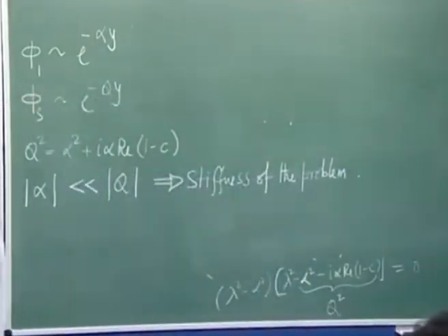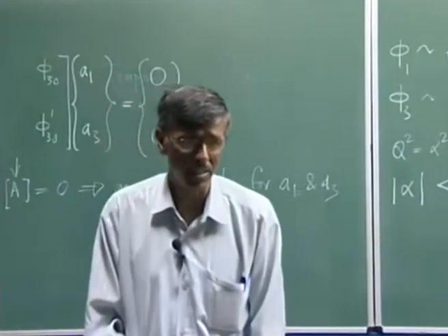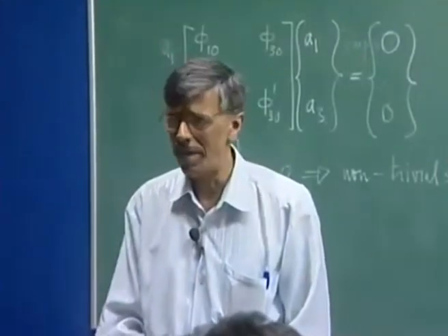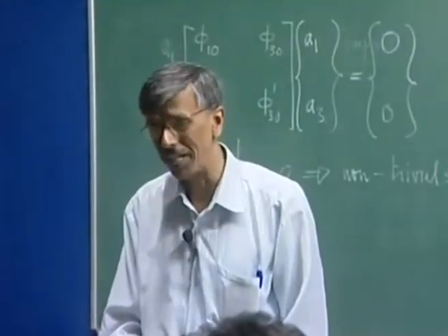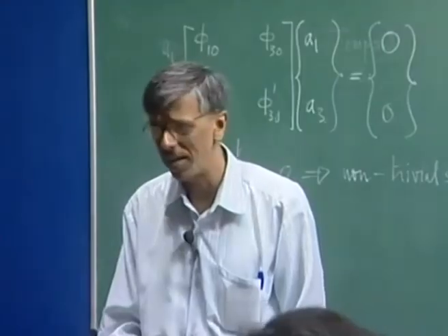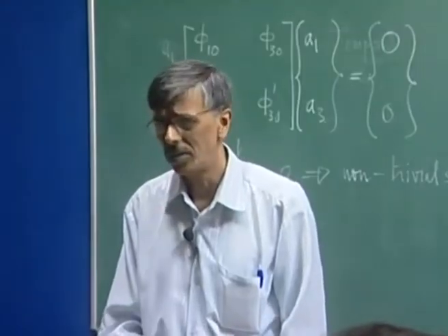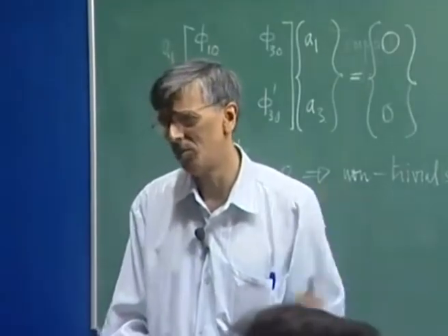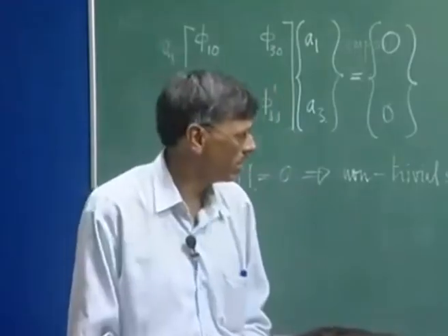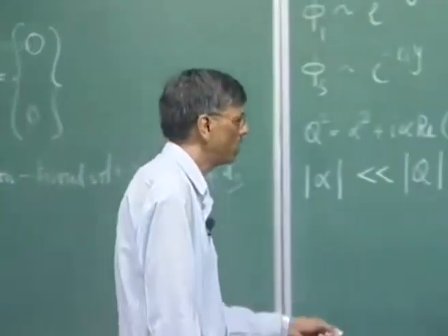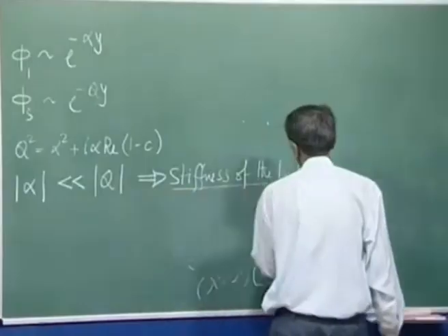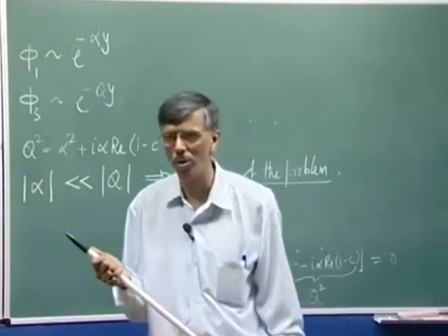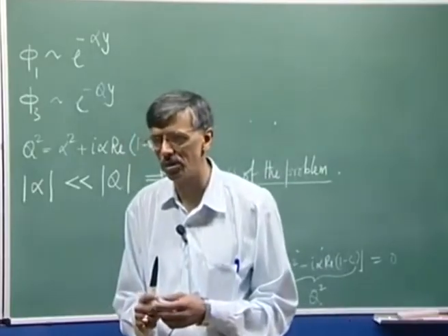And this is what we have talked about many a times, that this particular attribute of the solution makes it difficult to obtain it. I mentioned very clearly in the last class also that while the Navier-Stokes equation was solved long before we could really solve this. This is essentially due to this, and this is a topic of mathematics called stiff differential equation. So, we have to worry about how to solve stiff differential equations.